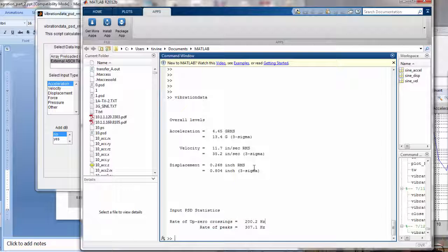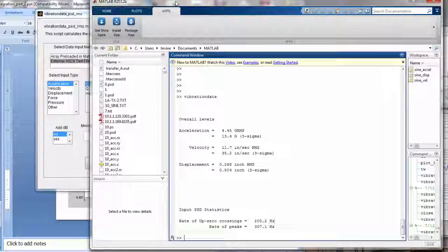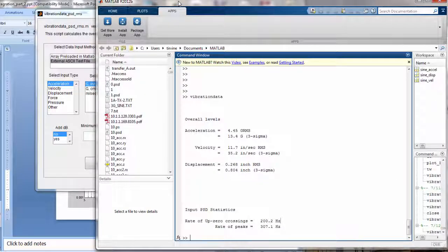There is a technique in vibration testing called peak clipping to limit the peaks to a particular sigma level. And I've never actually used that, but I'm aware that that's available. There are some concerns using that option with causing some distortion and a few other things, but for practical purposes, rather than doing this test in-house, we might have to go to an outside test lab that had a large displacement shaker.